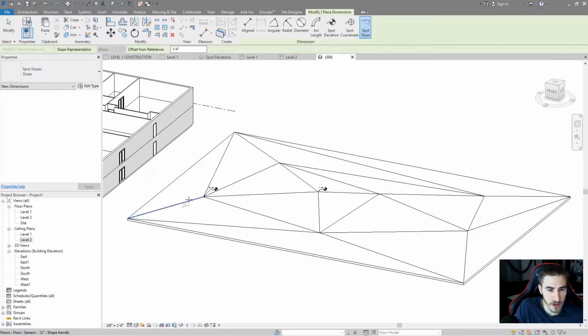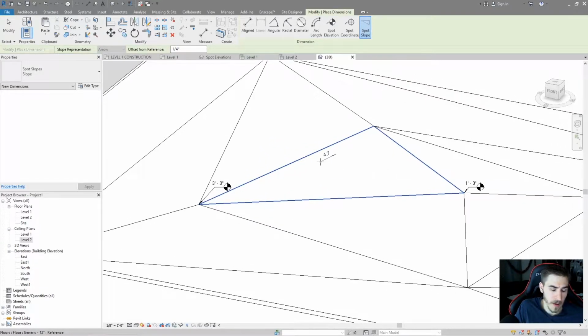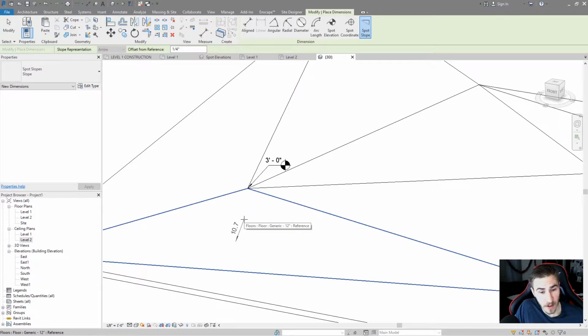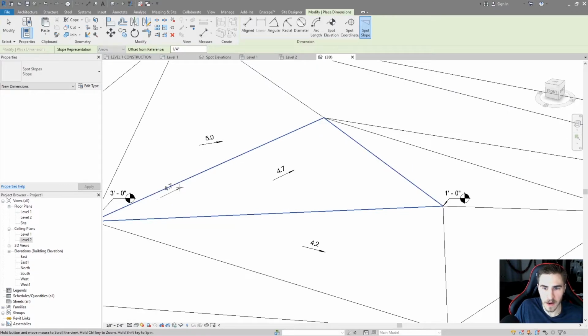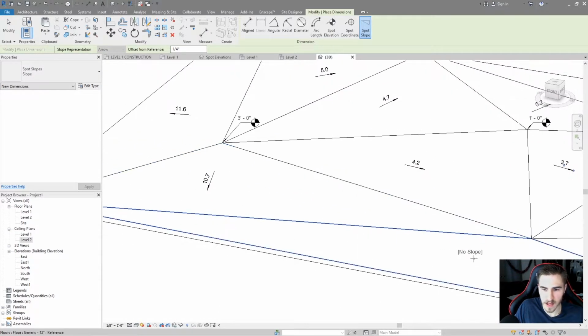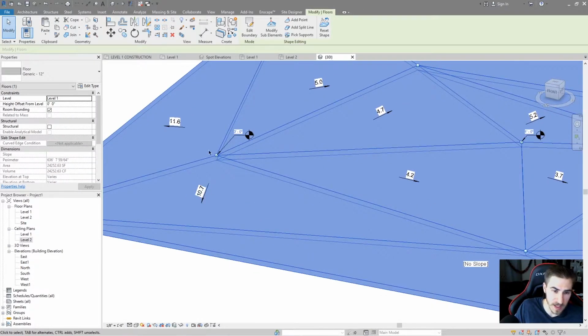I need to make sure that some of these slopes are, maybe it's a parking lot, maybe, the biggest thing might be if it's a path for egress. If it's on site, it needs to be less than 5%. So in this case, 5% there, that's fine. 10.7, that will not work. But the nice thing is that I can leave these values here, and I can continue to update the floor in this case. So maybe I need to work on this specific value.